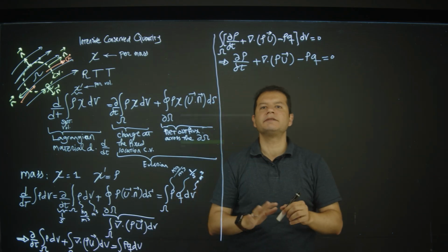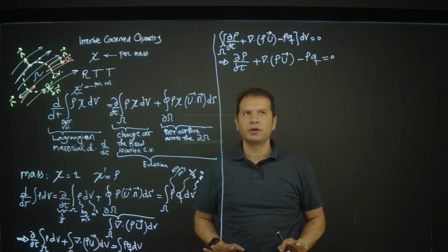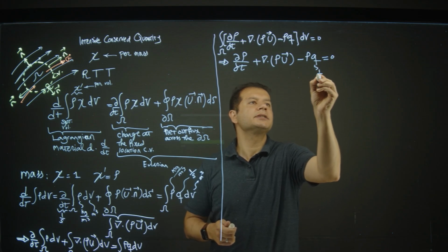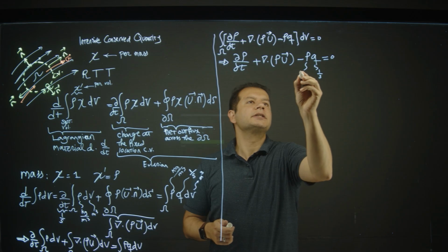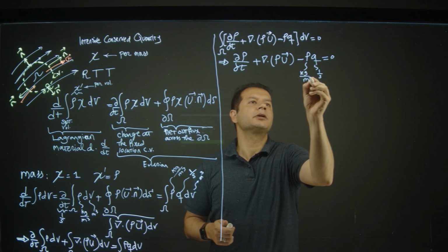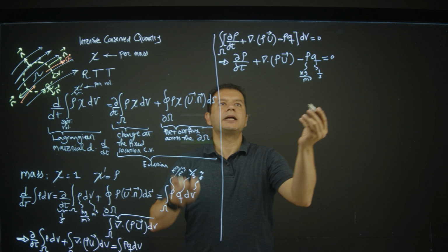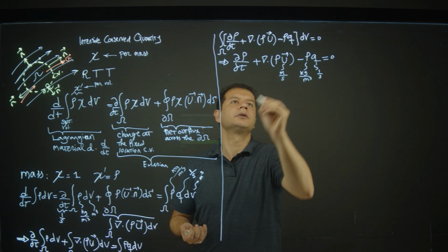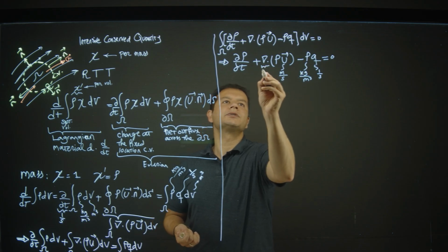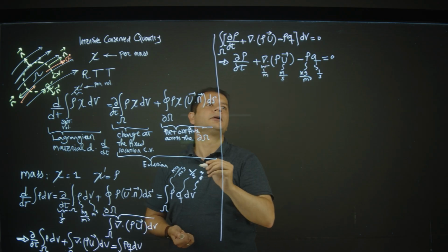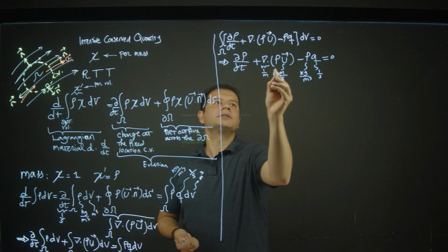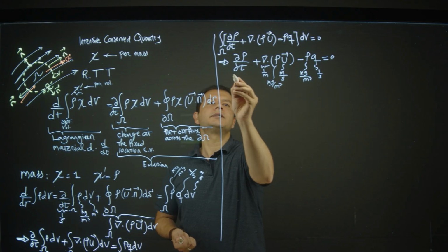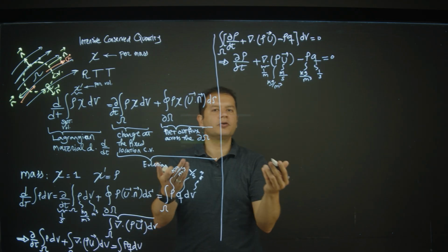And that's mass conservation in the most generic way. So units: Q is 1 per second, rho is kilogram per cubic meter, and that's all. The rest is very clear. U is meter per second. The divergence operator is 1 over meter, and density is already known to you, which is kilogram per cubic meter, and the same here as well. This is d/dt, which is 1 over second, etc.